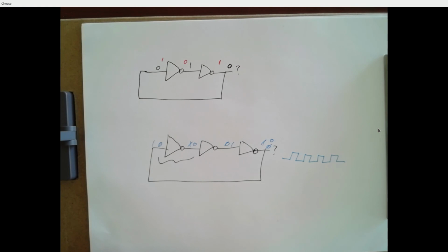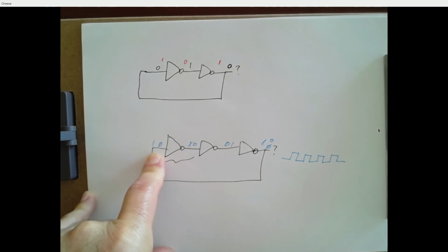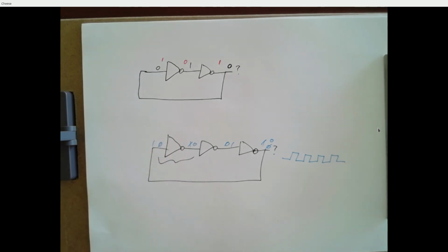Does that ever exponentially grow when it continues to go through this? No, it doesn't actually. Because this thing just sees a 0 or a 1, right? And because these are digital circuits, they take a range of input voltages and they say this is 1, this is 0. We don't get that kind of feedback effect. Now if this was pure analog, you probably would get what you're describing, where it starts feeding back on itself and the output gets bigger and bigger, or where it fades away. But we get a nice oscillation.